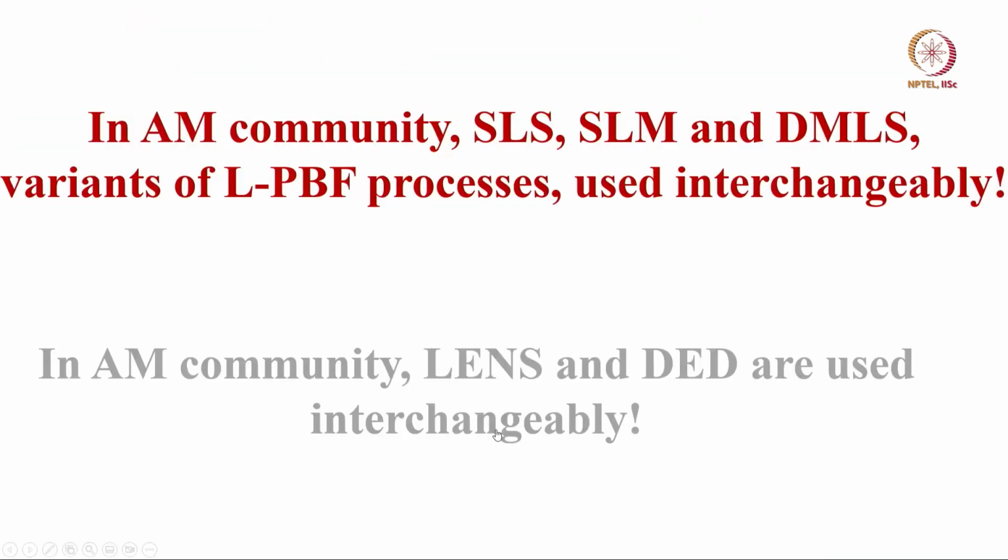So, in the additive manufacturing community, SLS, SLM and DMLS, selective laser sintering, selective laser melting and direct metal laser sintering or direct metal laser melting, are all variants of L-PBF, laser powder bed fusion processes, which are used interchangeably.